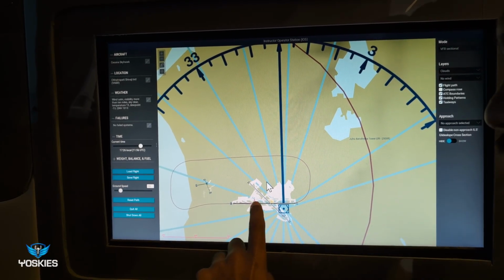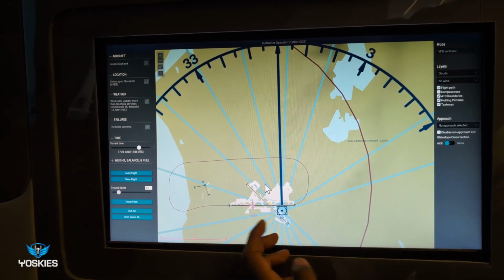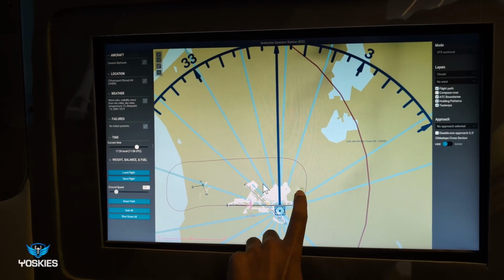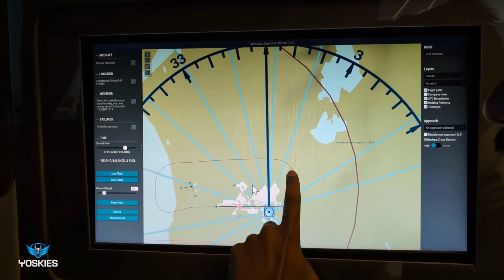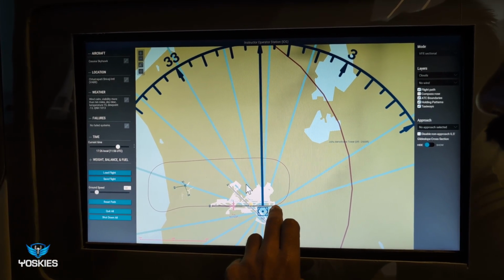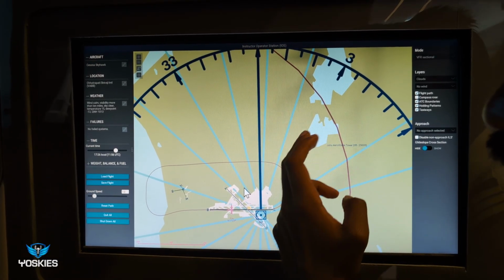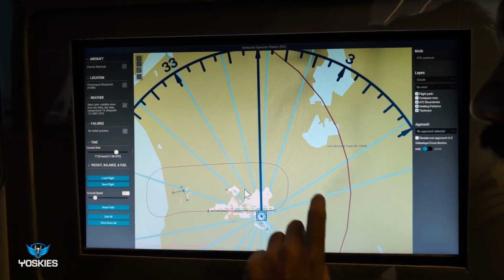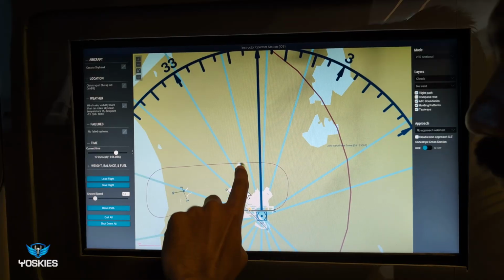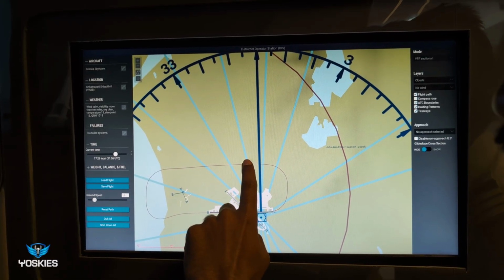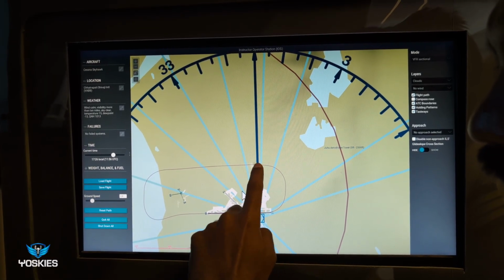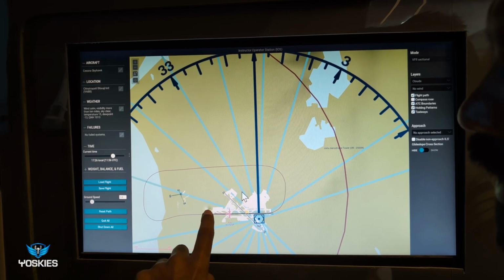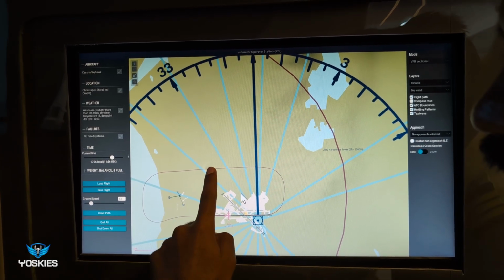Okay, so we will take off, and the first turn will be at 500 feet towards left. Then that is your crosswind leg. Then once you make 45-degree angle with the numbers basically, when you want to start your turn to the downwind. So when you are midfield left downwind is when you want to start your pre-landing checklist and then continue on 1000 feet. So when you are abeam the numbers is when you are going to start your pre-landing checklist.